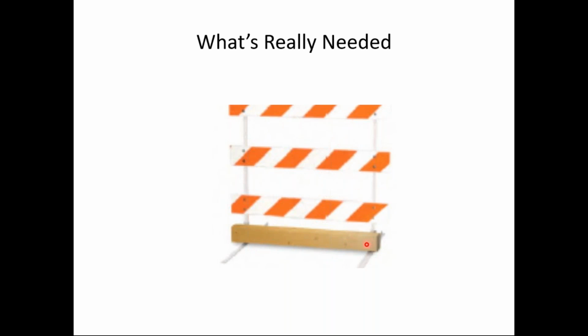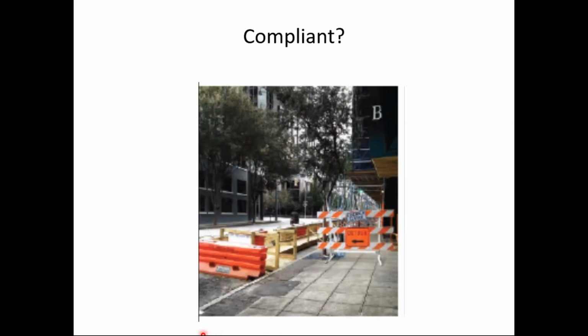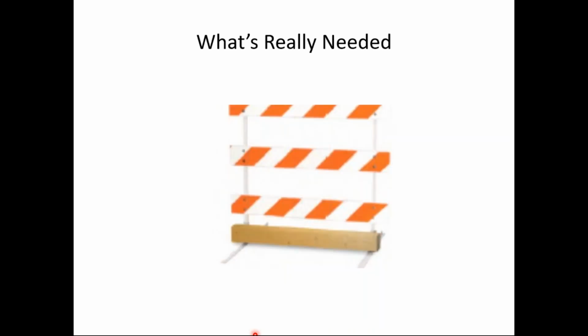type 3 barricade and added this board to it. So from a motor vehicle standpoint, this would not be a crash-worthy device. But I would say as long as it's being used in an application like this one, on the sidewalk where it's not likely to be struck by a motor vehicle, that should be okay. But keep that in mind if you'd be locating this near the traveled way where a motor vehicle that departed the roadway could strike this, recognize that that would not be a good situation because this is not a crash-worthy device from a vehicular standpoint.